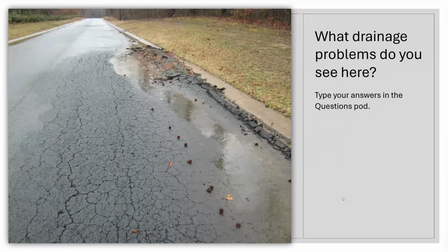Okay, well, what we see in the picture is that we have a lot of fatigue cracking. So there's already some damage. All of those cracks are avenues for water to soak down beneath the asphalt layer into the base and the subgrade. And so once that has happened, we've got a softened subgrade. Traffic loadings are going to press down and move the elevation of the pavement down, in addition to all the breaking and the potholes and that type of thing. You see all that asphalt, all those chunks, the rocks, they're all pushed over to the side. That's filling in the space around the gutter.